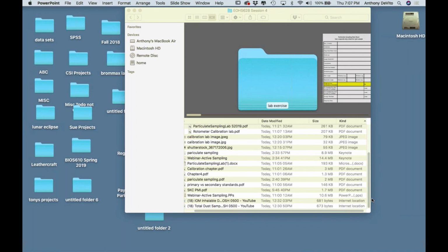And so work in teams, open up the cassettes. Here are your filters. Here are your backings. Here is a ton of tubing, and you have your cassettes already. Open them up, remove what's in them, assemble a new filter and backing into your cassette. Put it together and turn on a pump.